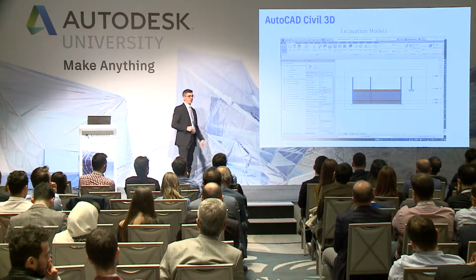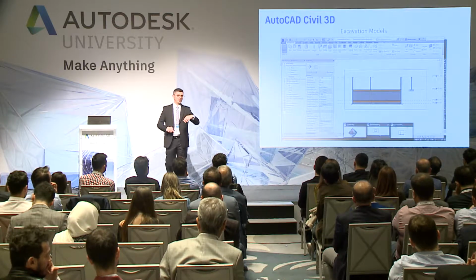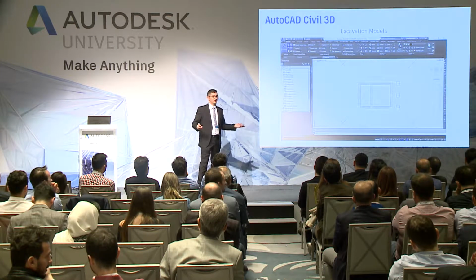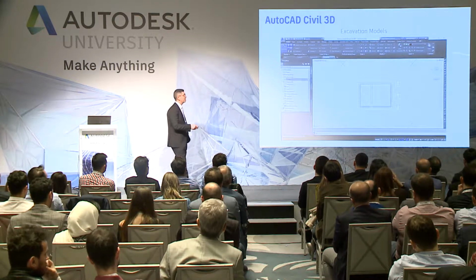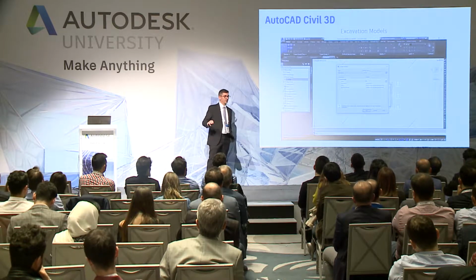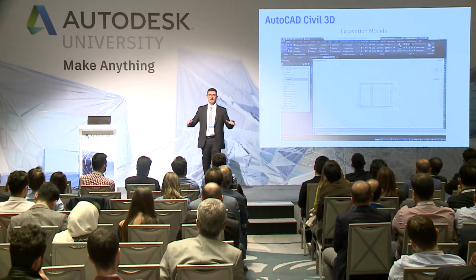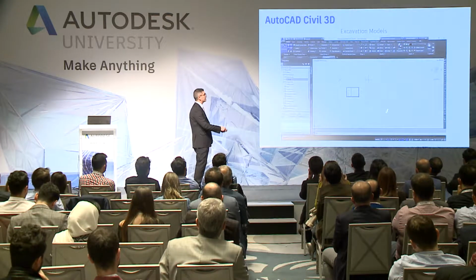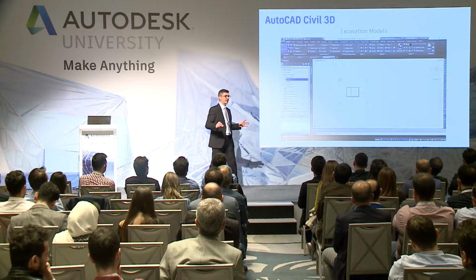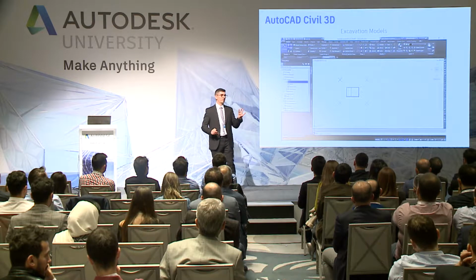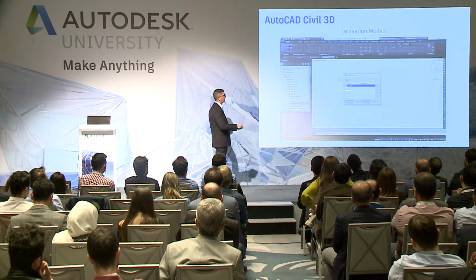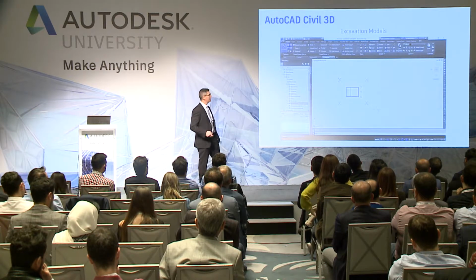Then I take this model, and I put the model inside Civil 3D. We can do it in several different formats. Maybe the basic is DWG. Then here we have it inside Civil 3D. The first step is always to create the ground, because I need to understand the basic elevation. In this case, I use only 4 points. If you start and you have no data, you can define first 4 points, or some point with elevation. Then I can create a surface from these points that are the elevation.